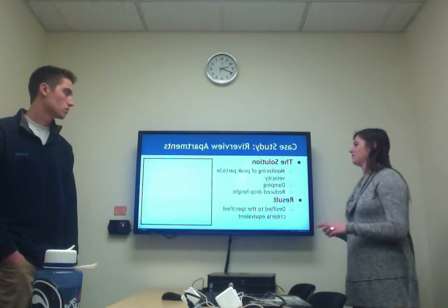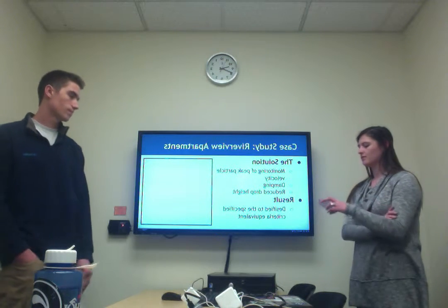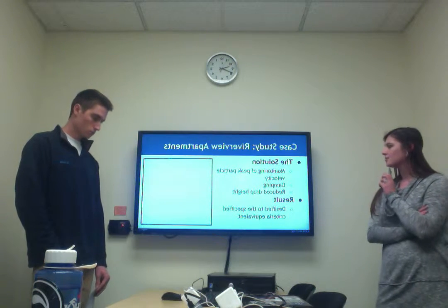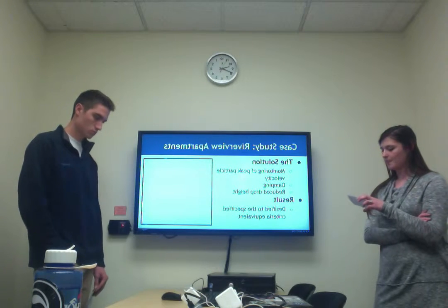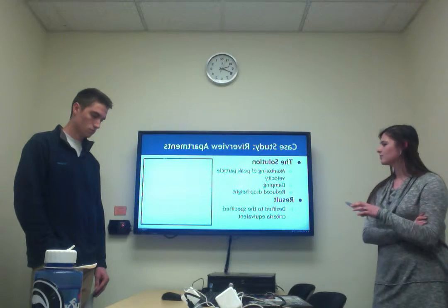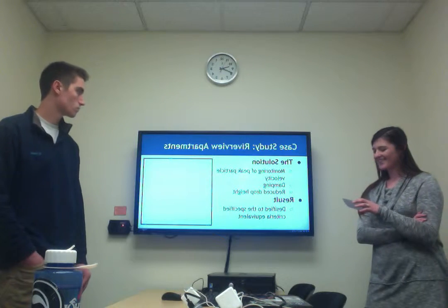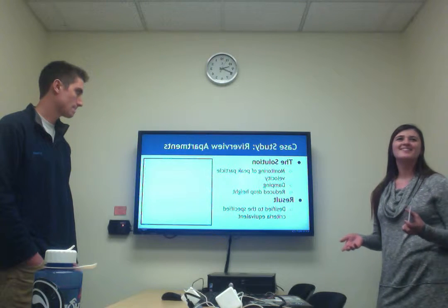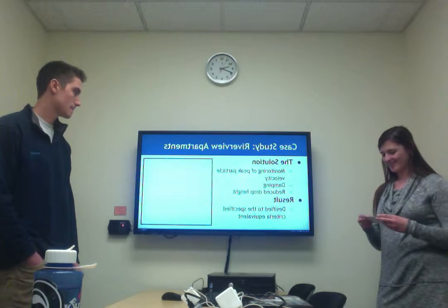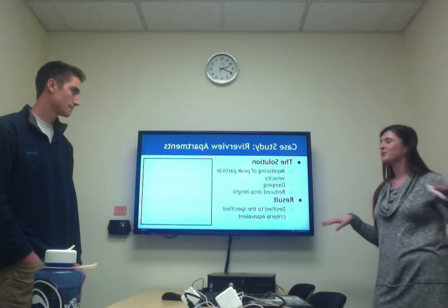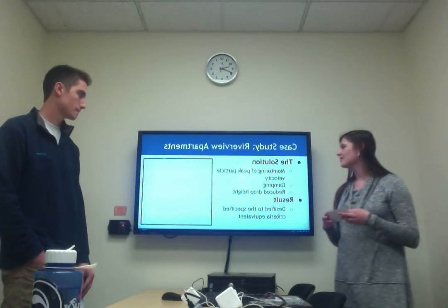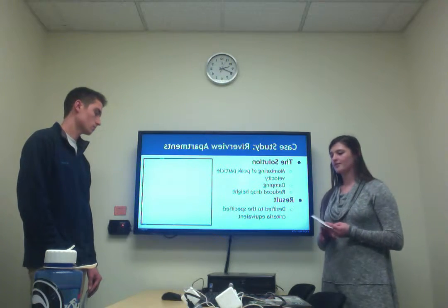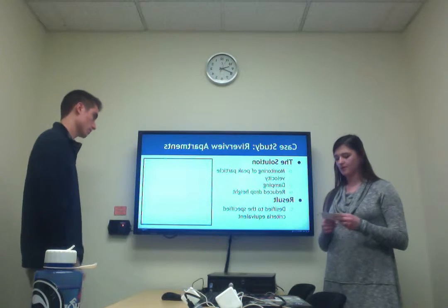Due to really loose soil, it was necessary for them to use the compaction because they needed to place shallow footings. But each drop creates waves laterally, which would impact the surrounding structures, which consisted of a restaurant, an office, and a sewer pipeline, which was the main concern.